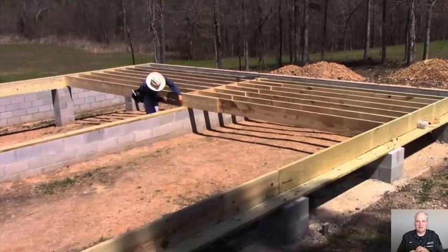So let's begin by taking a broad view. The structural goal of a house is to safely transfer the building loads through the foundation to the supporting soil. We've talked about this in the previous presentations. Remember when your science teacher said every action has an opposite and equal reaction? Well, every building load has an equal reaction load. If, when the loads of the house are combined, the house weighs more than the soil can support, the house, as we talked about, will sink.